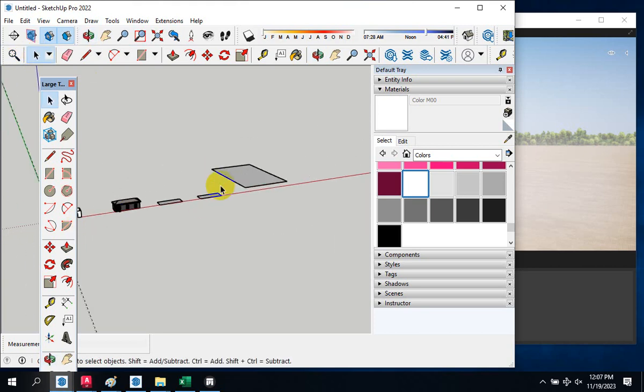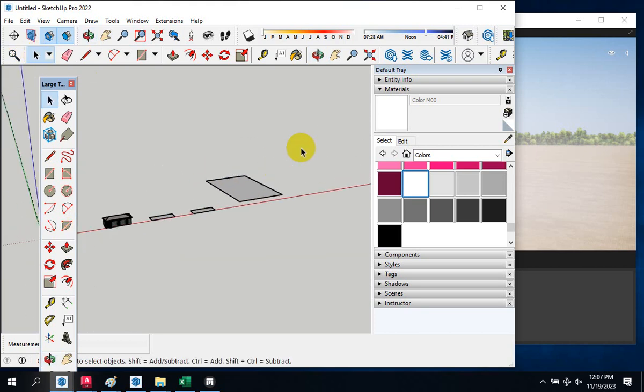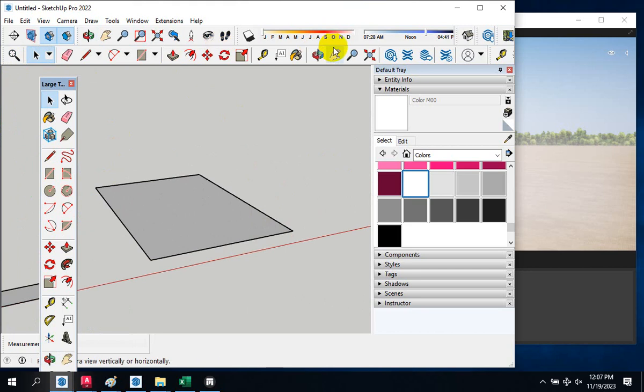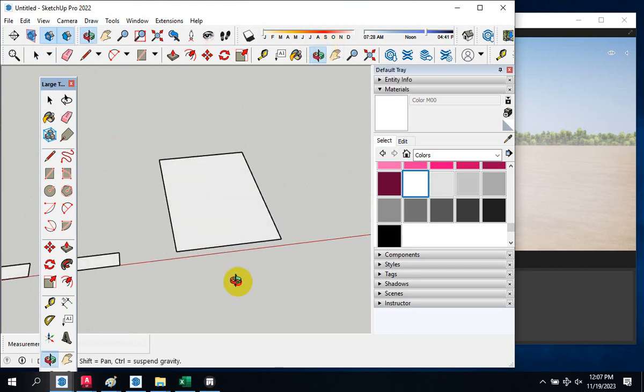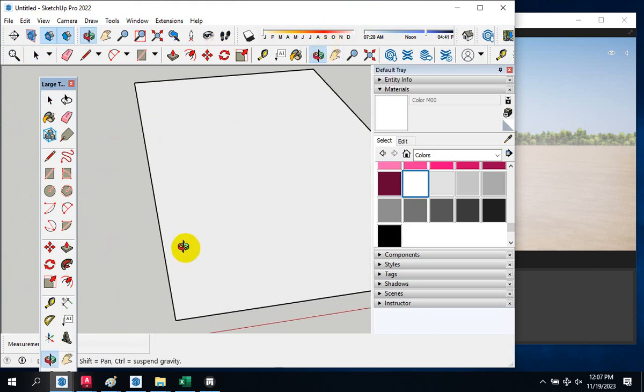So if we already have our site layout however you want it, there are some standards for building, like in Kaduna now, for example, you must give an allowance of 1.5 meters on the two sides, left and right. Then the front at least 6 meters.